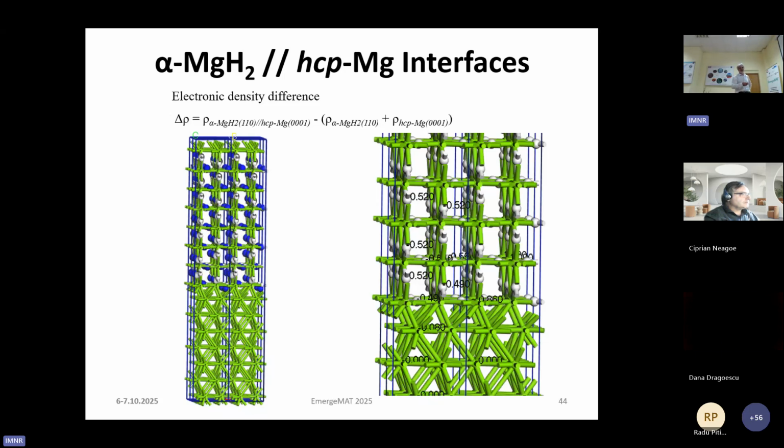So that means that at the grain boundary, the diffusion of the hydrogen is much higher than in the bulk. So actually, when we have such polymorphs, the diffusion of the hydrogen will be along the grain boundaries.